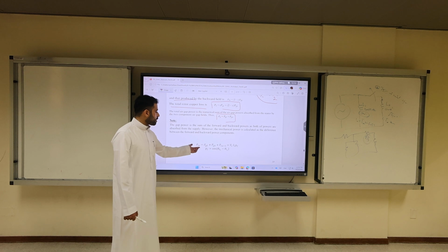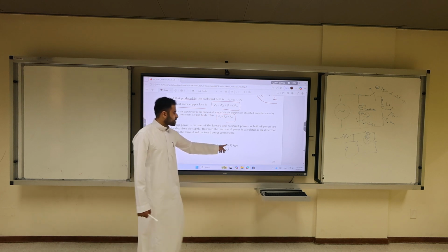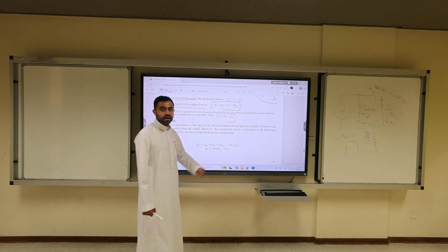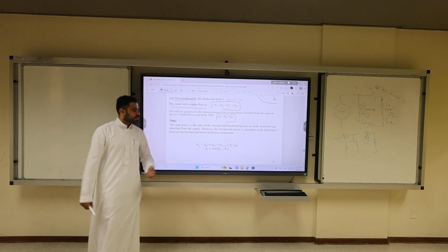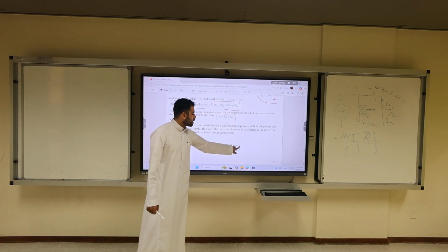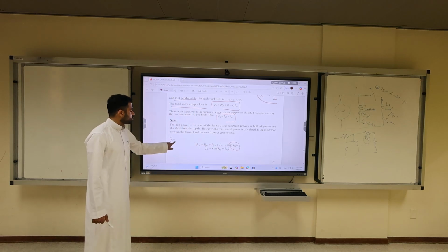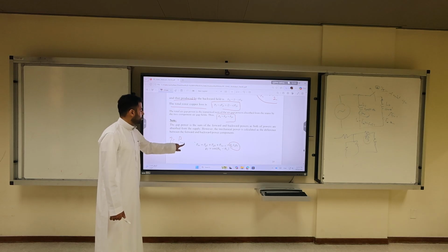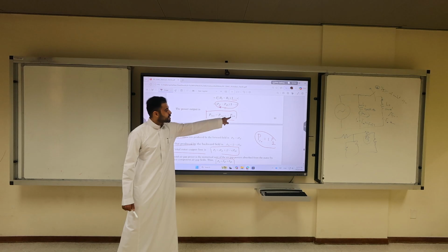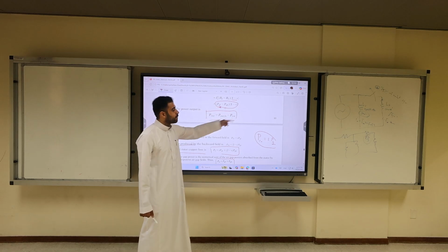Finally, what's your input power? It's forward plus backward plus copper losses, which is the supply. This is your input power. What is your power factor? It is cosine, omega, everything related to the supply. So basically, the input power or power factor can be calculated directly from the supply. And then your efficiency should be what? P output over P input. What is your P output? It is P mechanical minus P rotational. What's P mechanical? It's this thing. Rotational is given in the problem.